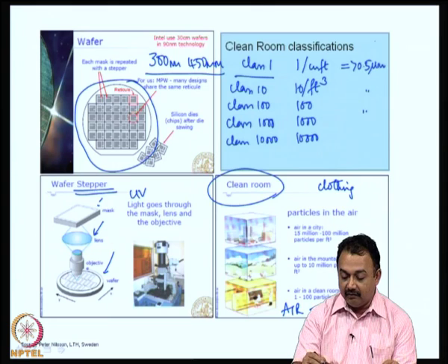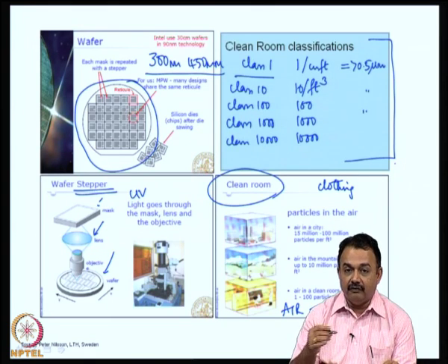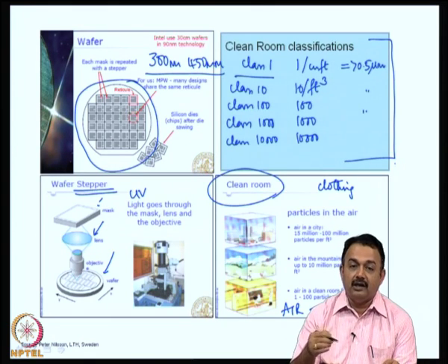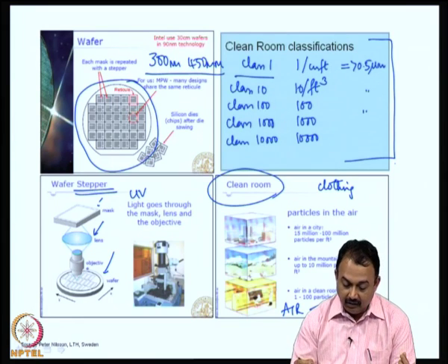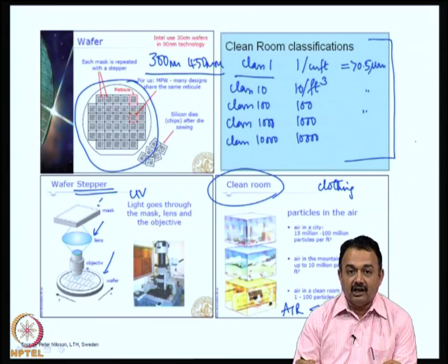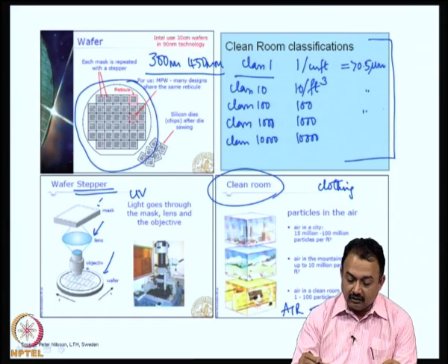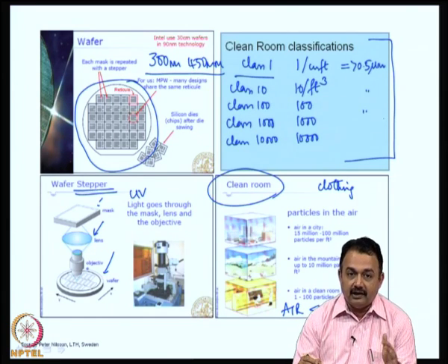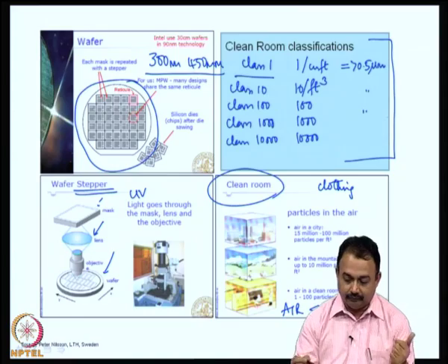So, in semiconductor manufacturing, you can also define different classes for different sections of the equipment processing. But for imaging, especially the photolithography, you need to have class 10 or class 1 clean room. So, the cost of wafer fab is one side of the coin, the other side is how to maintain your clean room regularly, because any dust getting into the wafer fab processing is going to damage the entire yield equations.